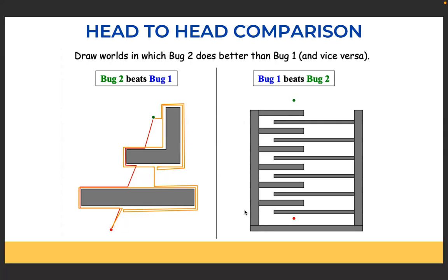Here, bug2 will never be able to reach the obstacle. Or even if it reaches, it will follow a meaninglessly longer path, and sometimes it may also get stuck at some positions. But the bug1 algorithm will entirely circle this full environment and then determine which is the nearest position to the goal and then leave from there.